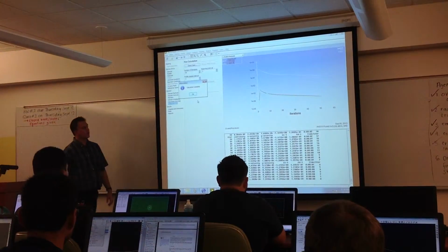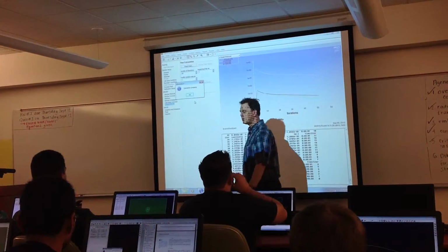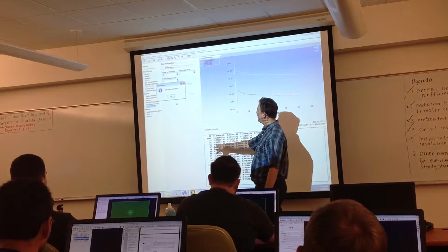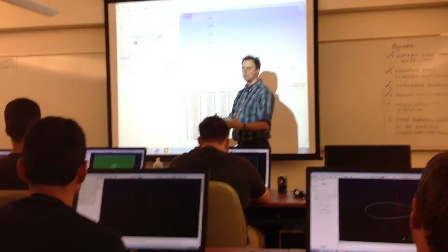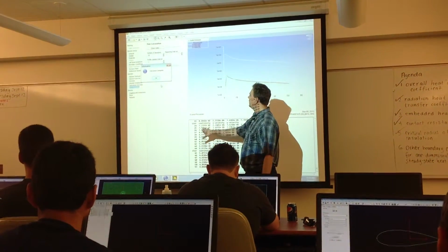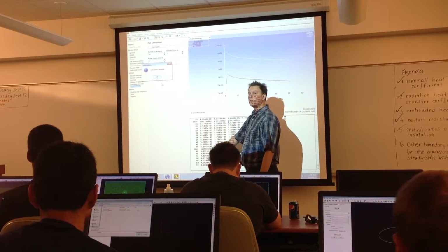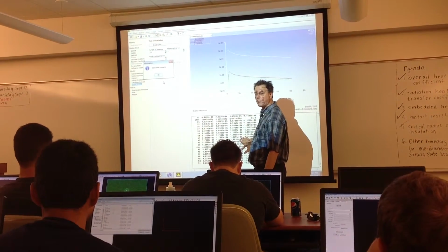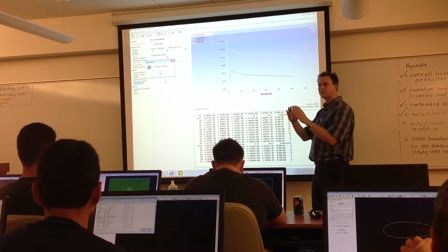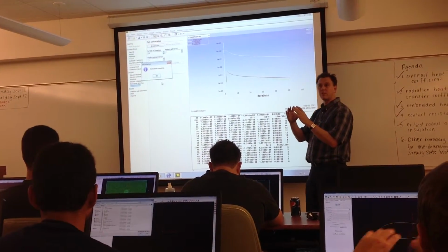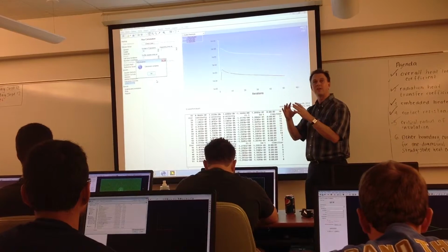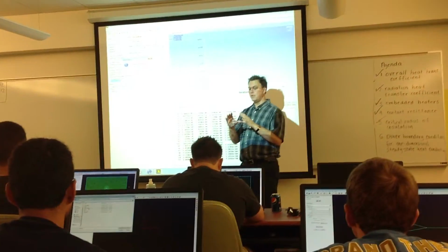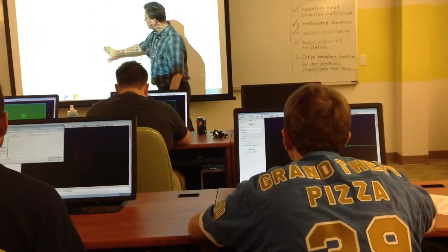Okay. Now what you're looking at here, these first three columns, these are called the residual. They're the measure of unsteadiness remaining in the solution with respect to the continuity equation, the conservation of mass, and the X momentum and the Y momentum equations. You remember for fluid mechanics, remember doing control volume analysis? That's really all CFD is, just control volume analysis applied to millions of cells. Taking the average of the unsteadiness in a given cell, you get these measures.